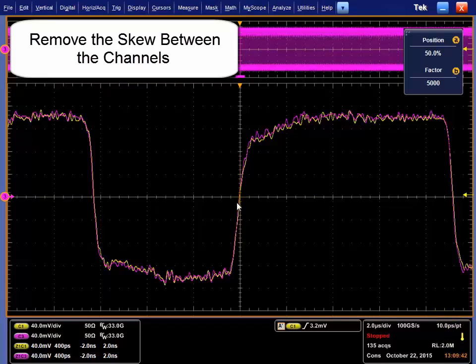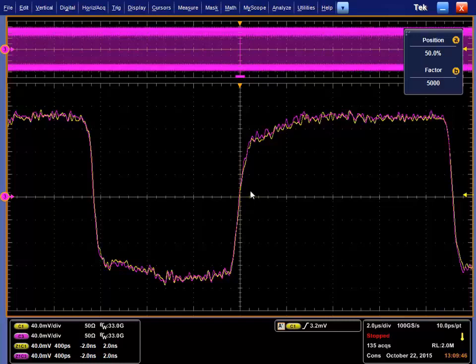There are a couple different ways you can check the skew. Again, as I stated earlier, I've got my signal going through a splitter so that I've got the same phase of signal coming down both cables, because I want to de-skew all the way to the ends of my cables. If that's the case, we have a tool that helps with that to be very accurate.